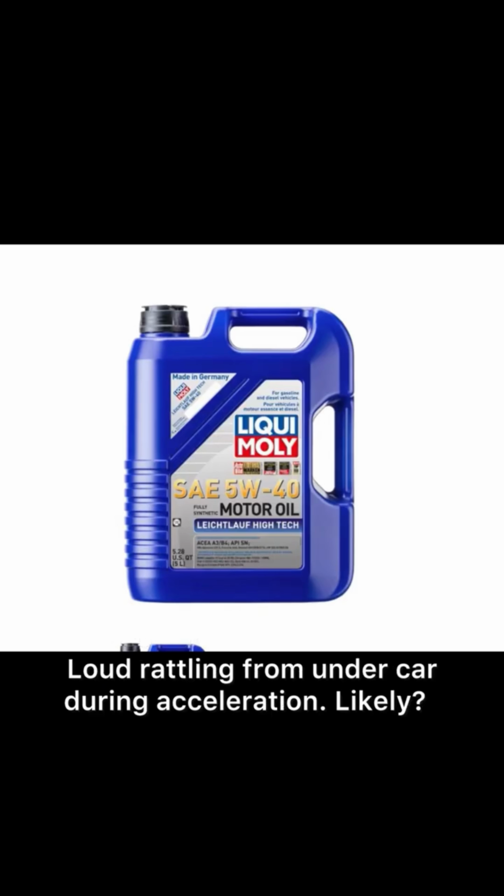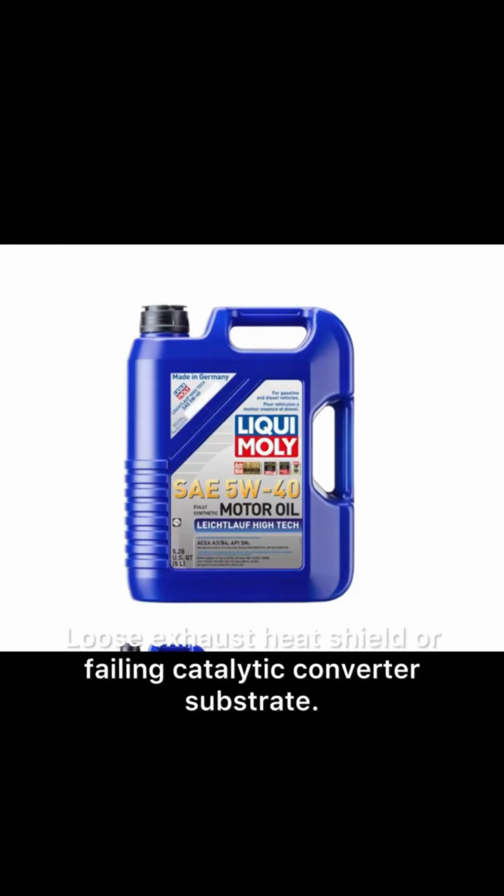Loud rattling from under car during acceleration. Likely, loose exhaust heat shield, or failing catalytic converter substrate.